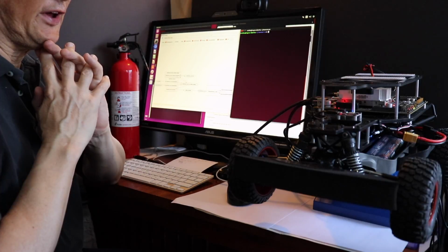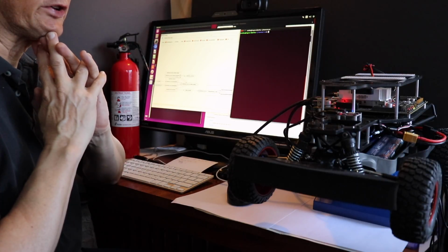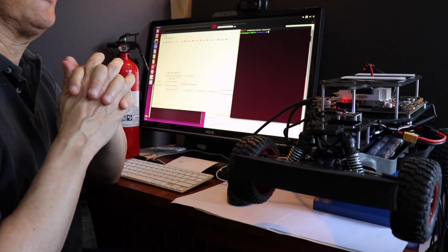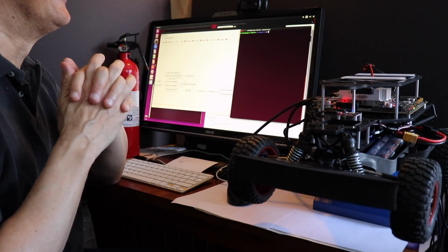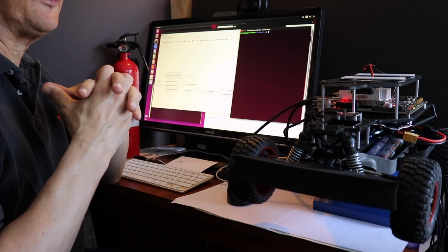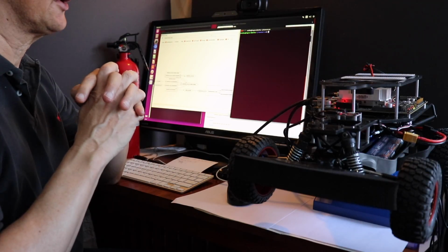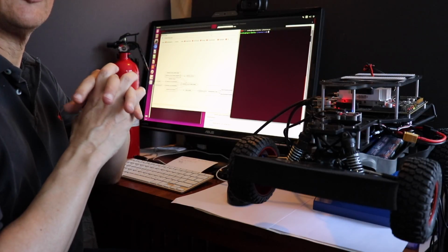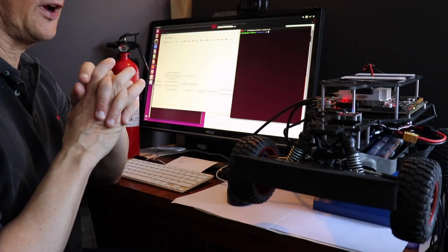So that was correct. In our little demo there, on our first attempt, you can see that the motor cogged. Cogging is kind of a technical term for it didn't work. This has to do with the way a brushless motor works. You can alleviate that somewhat with a sensored motor. In our second attempt, it worked like it was supposed to, but not probably how you would have expected it to work the first time through.